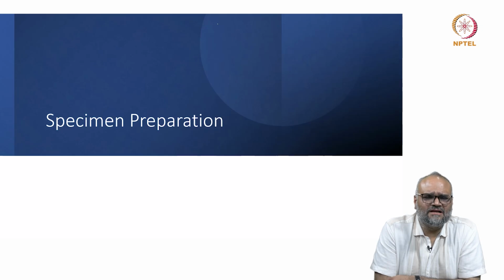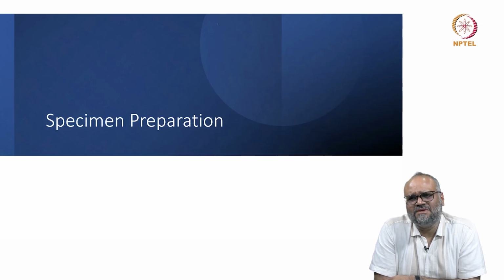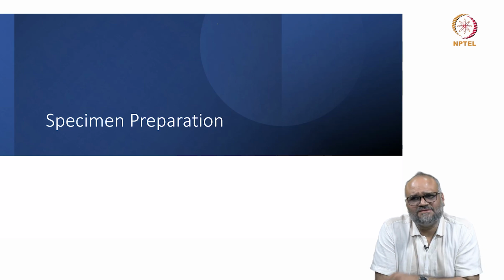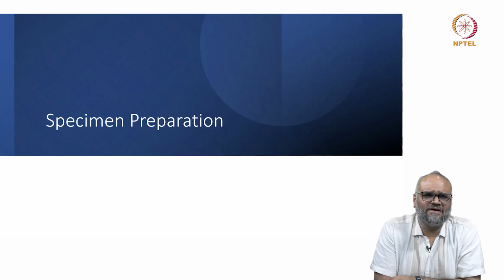Typically for most of the inorganic materials, this number is approximately the size of 100 unit cells stacked one over the other. And if I assume the size of one unit cell is approximately 10 angstrom, then stacking 100 unit cells would give you a thickness of around 1000 angstrom or 100 nanometers. And this is a ballpark figure for an element with an average atomic number of around 10 to 20, which gives you a reasonably good specimen thickness. As the atomic number increases, you want the specimen to be as thin as possible.